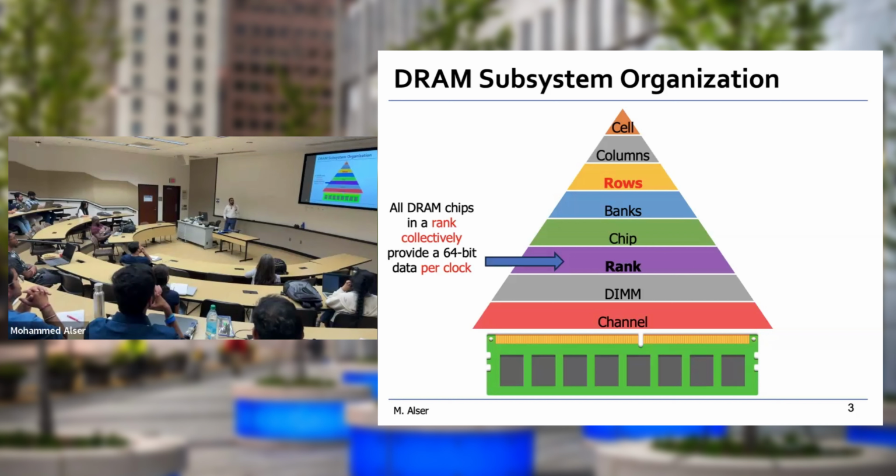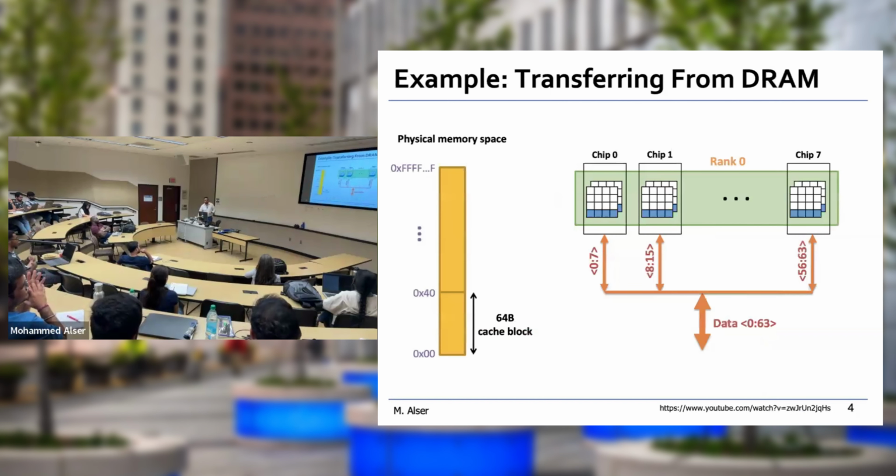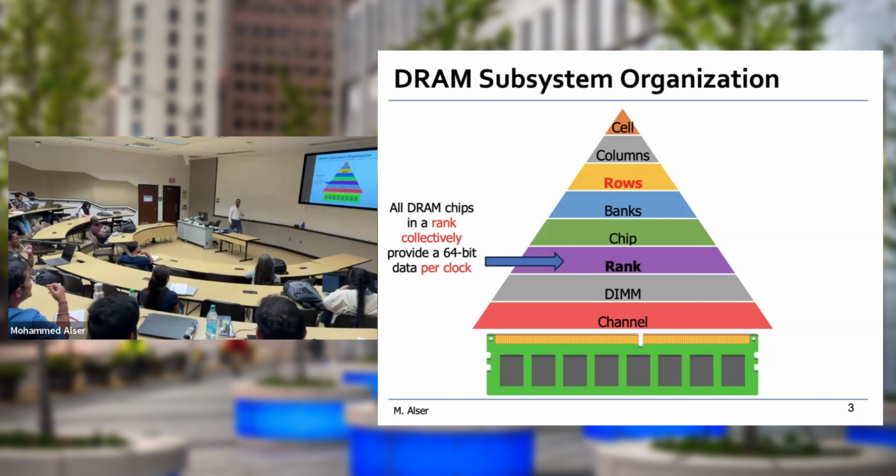Excellent. That's one. Instruction, we call it control. And so, data and commands. What else? Address. Excellent. So these 3 things are normally shared between the chips of the same rank. If it's a different rank, then it's not shared. That's why in a single clock cycle, all those chips can know that I want that address in that particular bank, so I can get back all this data.